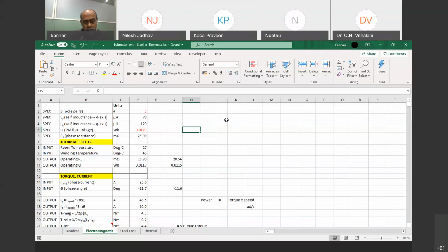So the simple way to measure these two things without damaging the motor is that I will take the motor that I want to measure, and connect it using what is called a coupling to the shaft of another motor, which I can make run at some known RPM. I can make it run at 1000 RPM, or 1440 RPM, or 3000 RPM, whatever.